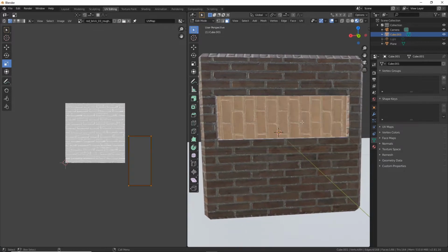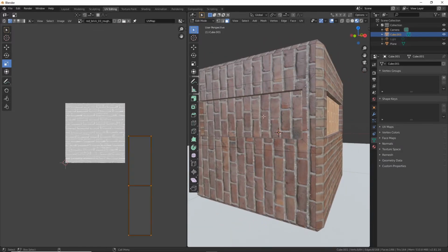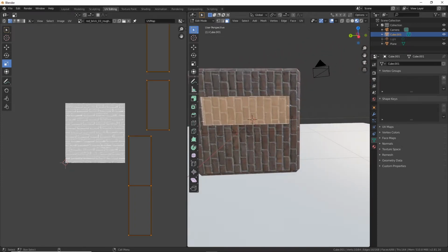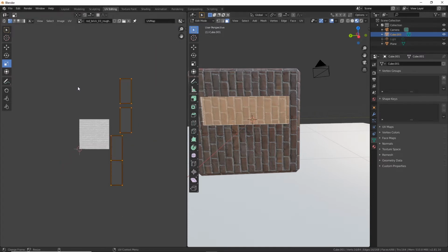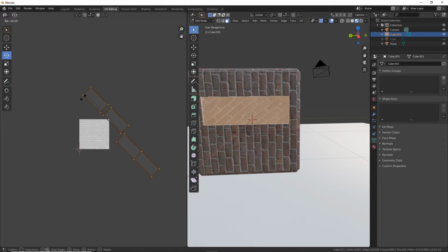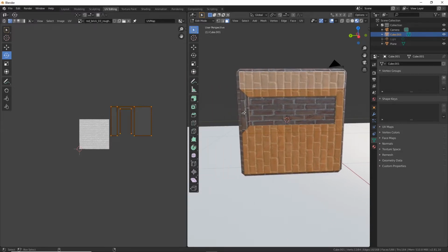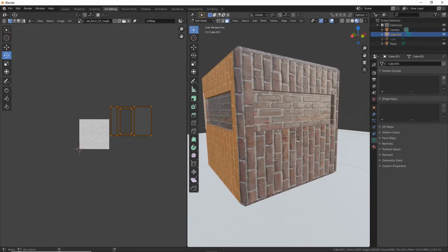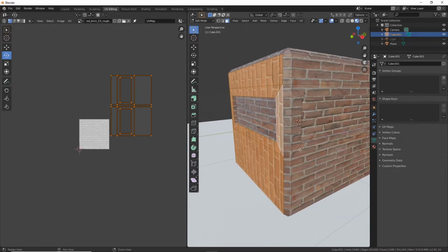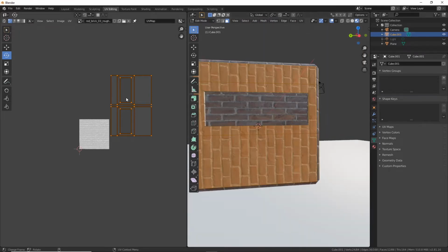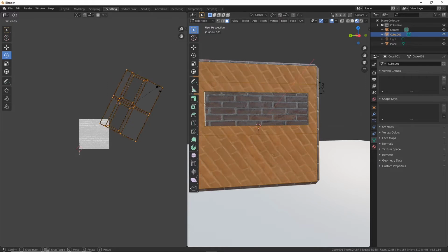So now, if you wanted to fix these that are turned sideways, facing the wrong direction, so let's say I want them to go horizontal. I just selected all those faces. I can hit E over here in the UV map mode and hold down Control so that it locks to angles, and then just rotate it 90 degrees. I can do the same thing with the sections that seem to be facing the wrong direction. This one's horizontal, and that one is. Then just take those and E, rotate, hold down Control.